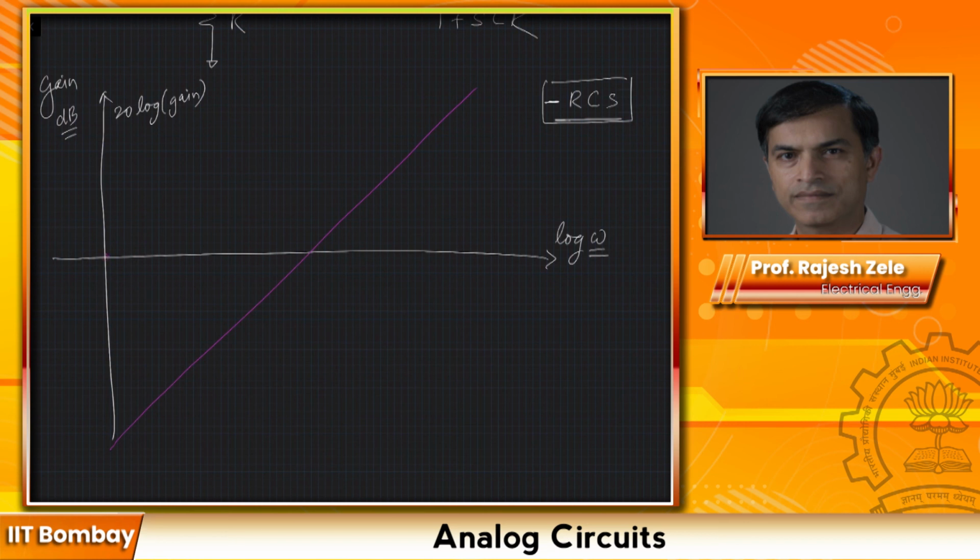So this is 0 dB. And as you would have guessed, at S equal to 1 over RC, you will have the 0 dB frequency. So this would be 1 divided by RC for the ideal differentiator. Okay. So just this one particular intersection will define this differentiator circuit.